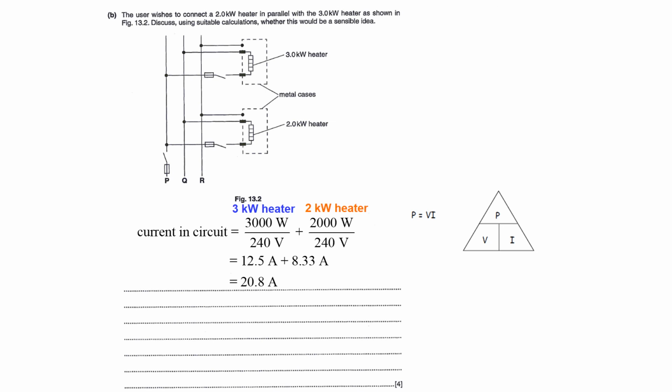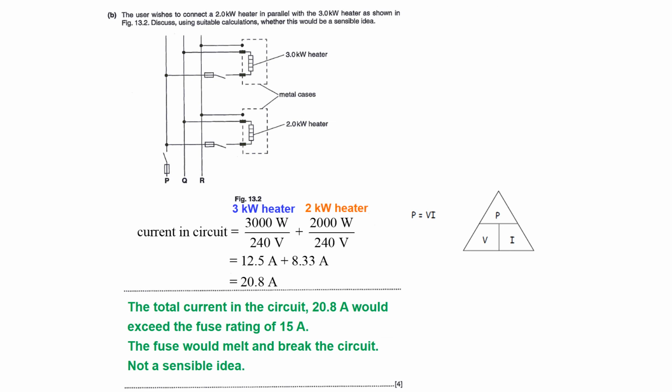This circuit is connected to a 15 ampere fuse. Therefore, this is not a feasible idea, as the total current in the circuit, 20.8 amperes, would exceed the fuse rating of 15 ampere. When that happens, the fuse will melt and break the circuit.